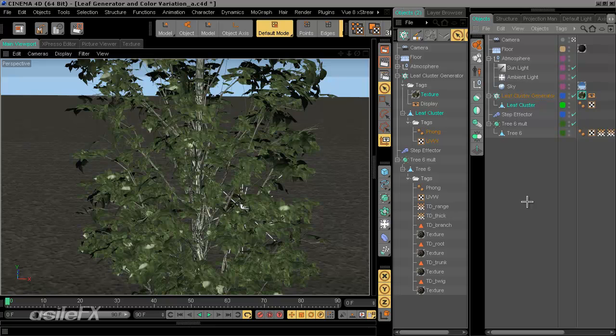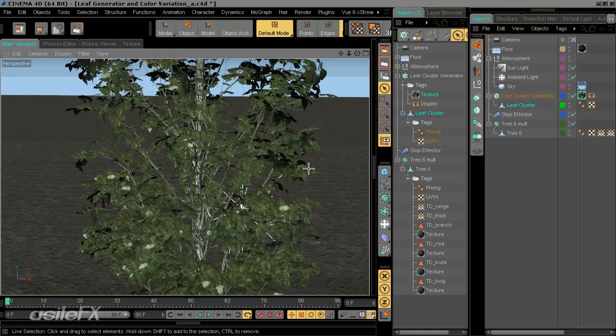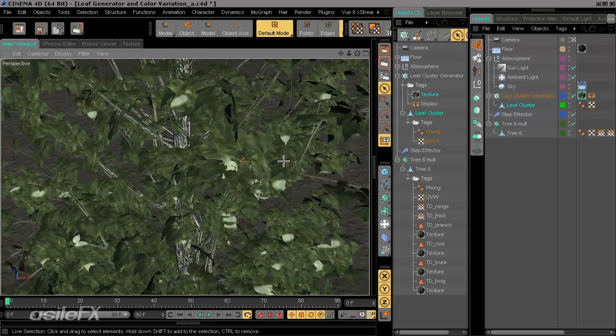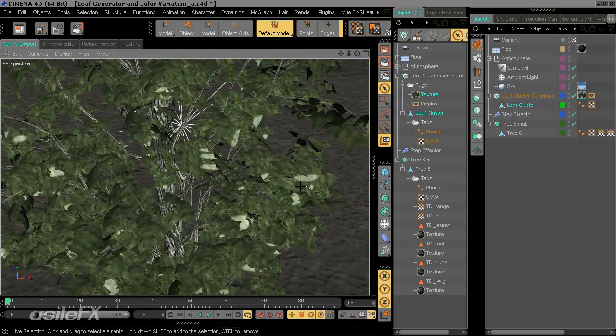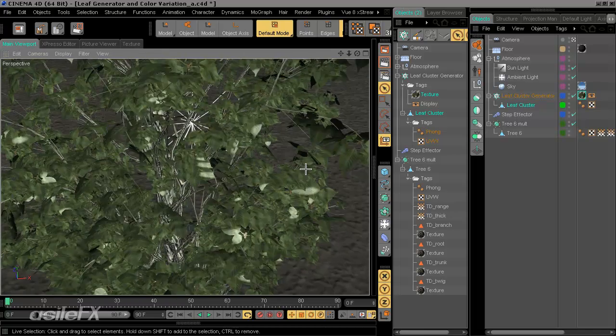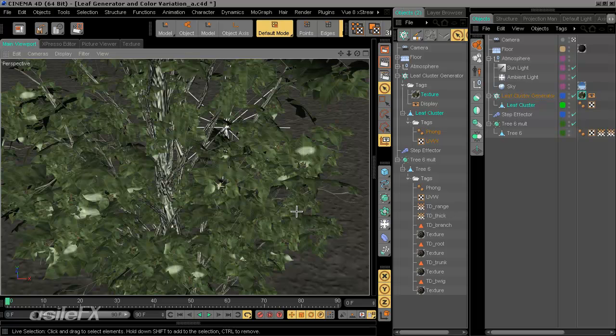a different scaling system or a different coordinate system for the texture, making it relative to the size of the clones rather than just the individual object that's being cloned. So we also need to set up a different kind of texture in order to lock some of the primary values, being the color and the alpha and all of the main maps to the UV, but open up the variation to affect within more of a world scale. Because otherwise, we're still going to end up with that repeating look on every single leaf.